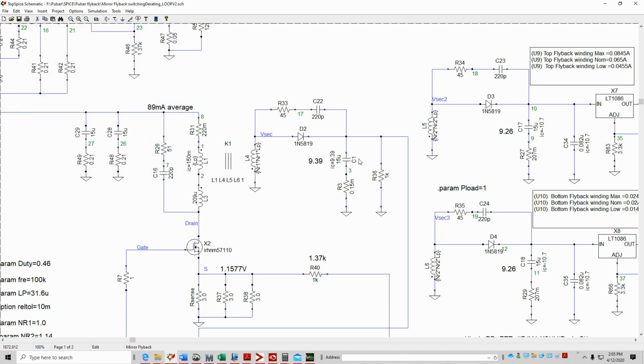Okay, and I want to reiterate or make you aware that when the value of the capacitor is on the left side, then the top lead is the positive. This would be the negative. So just remember that the value on the left means that the top is the positive. Otherwise, if this is backwards, then you would have to initialize this as a negative to flip it. So that's very important to get the right polarities.